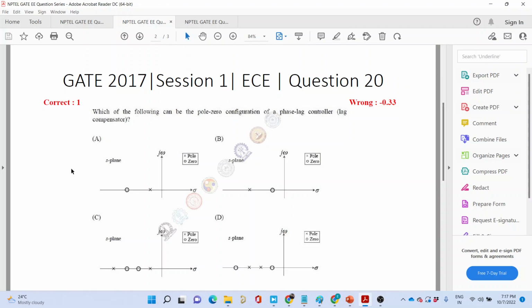Dominant means what? It contributes more to the performance of the system. The one which is more responsible for contributing to the response of the system. So the one which decays faster contributes less. Absolutely, yes. Because at the end of the day you are looking at the steady state response and also the transient response, but the one which is decaying down faster, you're not worried about it.